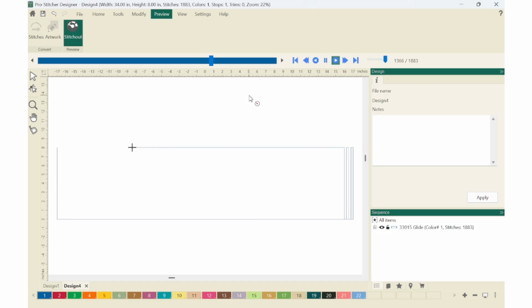So the two things: first of all, if it's a closed shape, you can right click and split line, and that will move your start point as long as it's a closed shape. If it's not a closed shape, then if you do the split line, you are going to have to reconnect the different pieces. But wherever the ending point is that you want, you should move the line just a little bit so that it doesn't connect at the point that you didn't want it to start with.